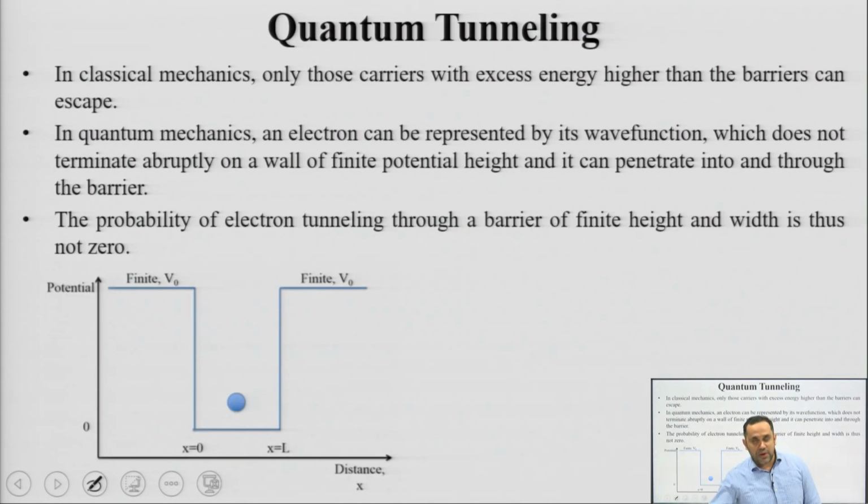In addition to thermionic emissions, many modern semiconductor devices work on the principle of tunneling. Now, whenever there is a potential energy barrier, classical mechanics would tell you that you have to apply an energy at least equal to that potential barrier height, so that charge carriers are able to surmount this barrier and move to the other side and produce current. There is another possibility: instead of crossing the barrier, the charge carriers actually tunnel through the barrier. This phenomenon is known as quantum tunneling.